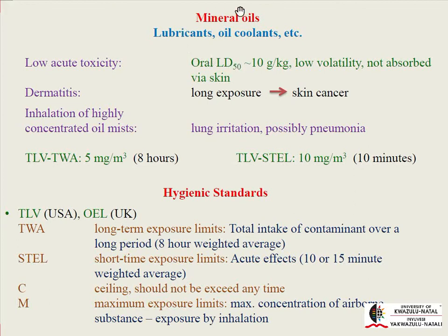Okay, and lastly, you get the issue of mineral oils, which typically have low acute toxicity. They're also not absorbed via the skin. However, over very long-term exposure, you can end up with skin cancer. It's an irritant on the surface of your skin. And if you inhale oil mists, that can result in lung irritation and even pneumonia.